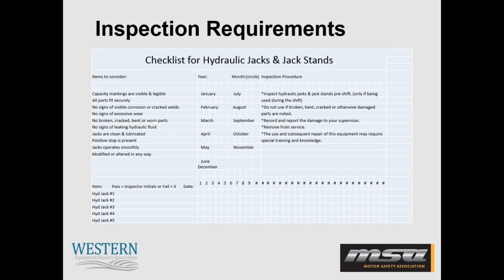So you can also make your own type of checklist to check your lifting devices at your facility. And if you are doing so, just always be sure you're checking for excessive wear, any cracks or welds, any visual damage, any loose or missing parts, and especially for the bottle type jacks and hydraulic jacks, make sure there are no leaks or oil around or built up on the jacks from residue. So that'll give you a few tips for some of those inspection requirements for jacks and lifting devices.